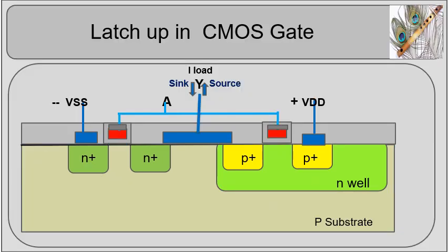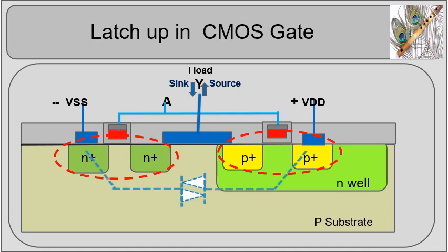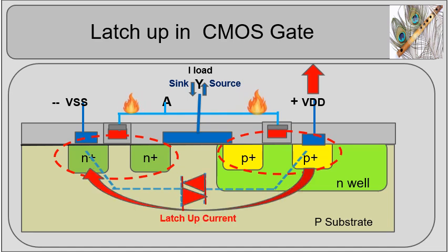The figure shows a typical CMOS inverter gate structure. It employs N and P MOSFETs and realizes various logical functions. The input signal at A drives both the MOSFETs and produces an output at Y. PMOS provides the source current and NMOS sinks it. From the figure we observe the presence of a parasitic latch across the logic gate supply. When the supply voltage becomes greater than the latch breakdown, the latch switches on and creates a short circuit across the supply. In this state of operation, unless externally controlled, the gate draws short-circuit current that leads to a catastrophic failure.